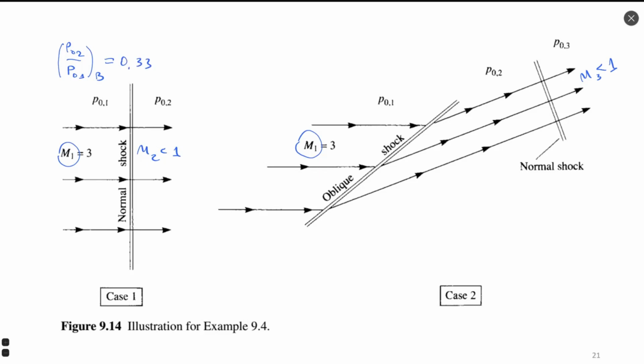So this is the result of using appendix B, or in the same way we can calculate flow according to the theory of normal shock wave. This ratio of stagnation pressure is given as an analytical solution, as you might know, right? Okay, so this efficiency is 33%. What does it mean to us? That when flow transits through a normal shock wave, it loses almost 70%, 67% of its energy is lost.